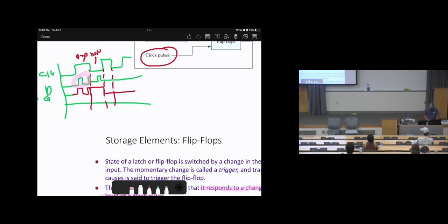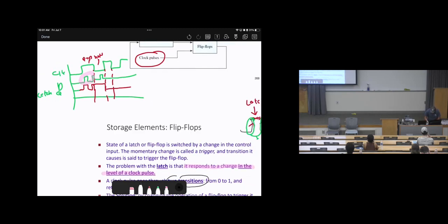However, in the flip-flop, our target is to look at, let me assume, the rising edge. In the flip-flop, we need to detect only during the transition from low to high. This is called the rising edge. So at the transition from low to high, you will realize D was on. So here, for example, it will be 0, then it will be on.